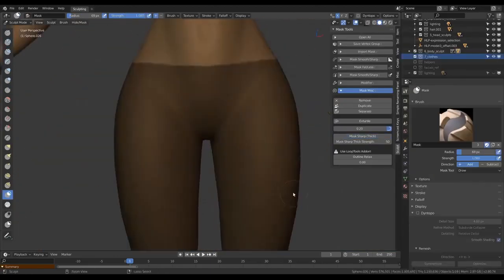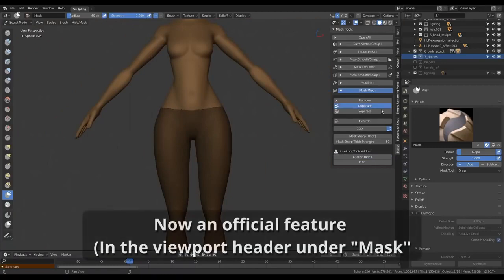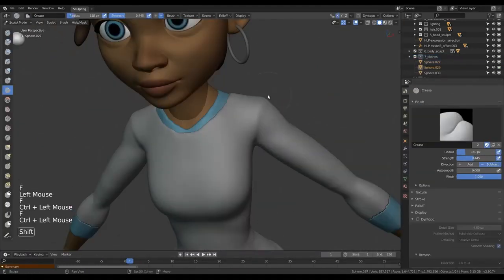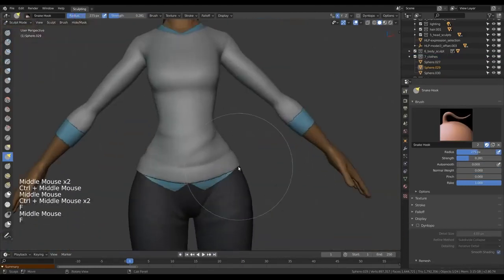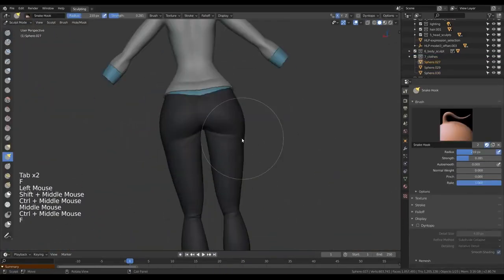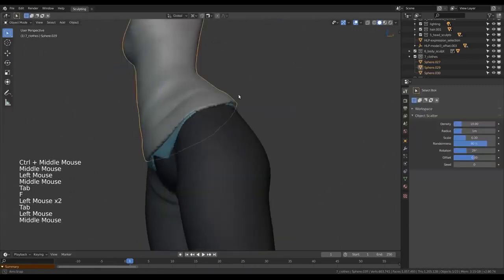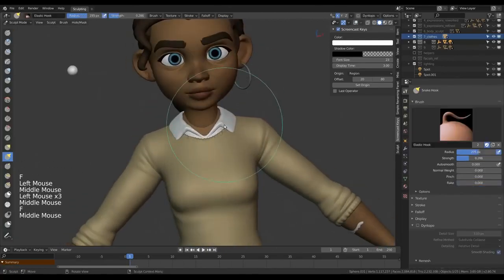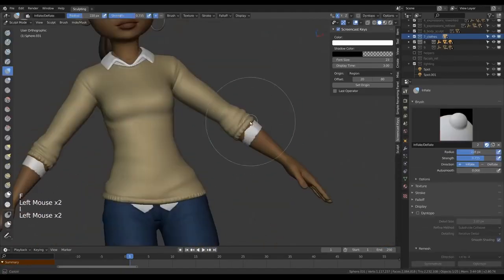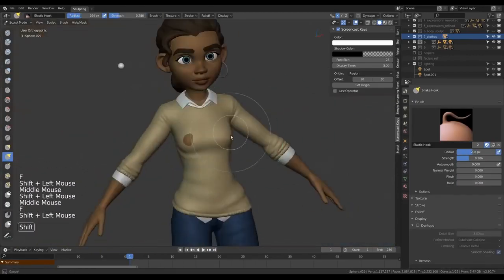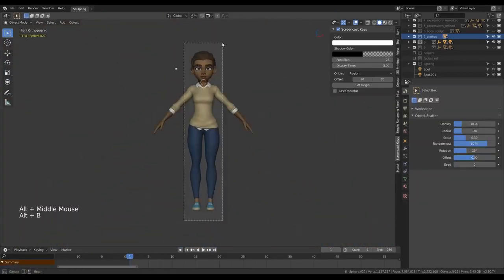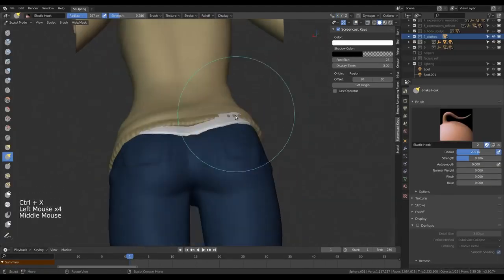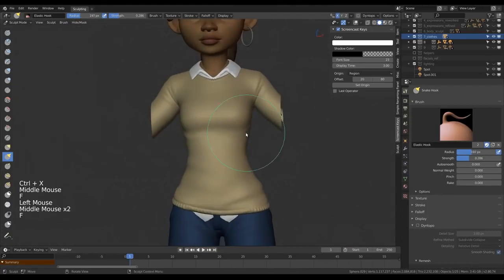For the clothing, it's again good to extract new objects from masks and refine them further by adding folds wherever there should be compression and stretching in the fabric. Vertex colors will again help you with your impression of the character so far, and you get to experiment with different color palettes. If you decide to change the overall proportions of the character, it's easier to merge all the objects of the body together and adjust everything together. Just be careful about any modifiers you might have still active. Afterwards, you can split them into individual objects again with the shortcut P in edit mode.